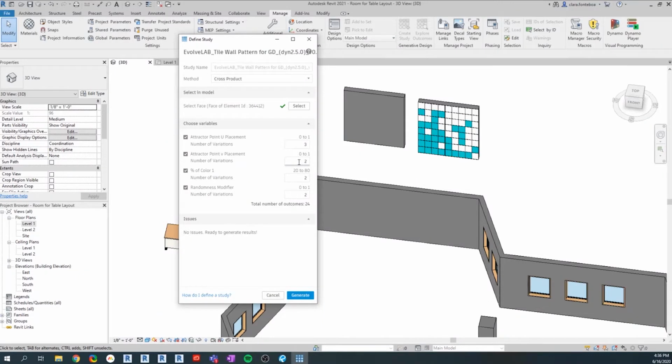So I'm going to put this as it's checking. If you look at the first pass, it's going to do 0, 0, 0, 0. Then it's going to do 0, 1, 0, 0. Then it's going to do 0, 1, 1, 0. So it's going to try every possible combination, like picking a lock. That's what the cross product does. It tries just everything depending on how many iterations you choose. So if you have 2 for each one, it's only going to try 2 combinations for each one of these inputs.